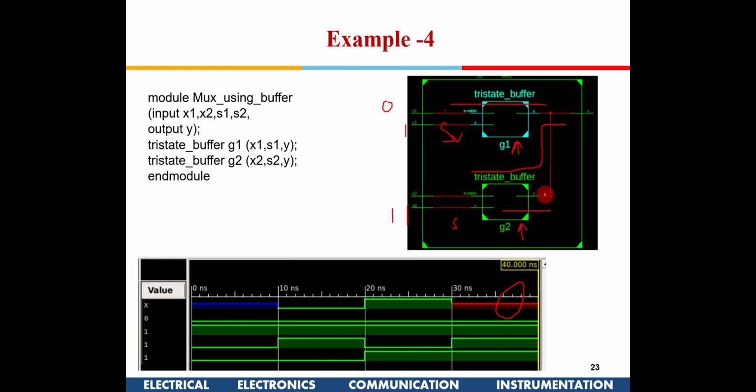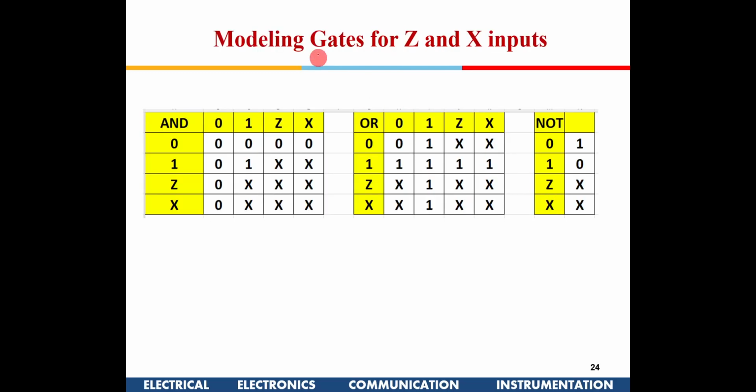Okay, so you have to do a detailed verification also, right. Now if you see each of these gates, the actual model used by these simulators is not binary, whereas it has got all the inputs, right: 1, 0, z and x. Okay, 1, x, z, and for an AND gate, if you see here, the output is 0, 1 and unknown.